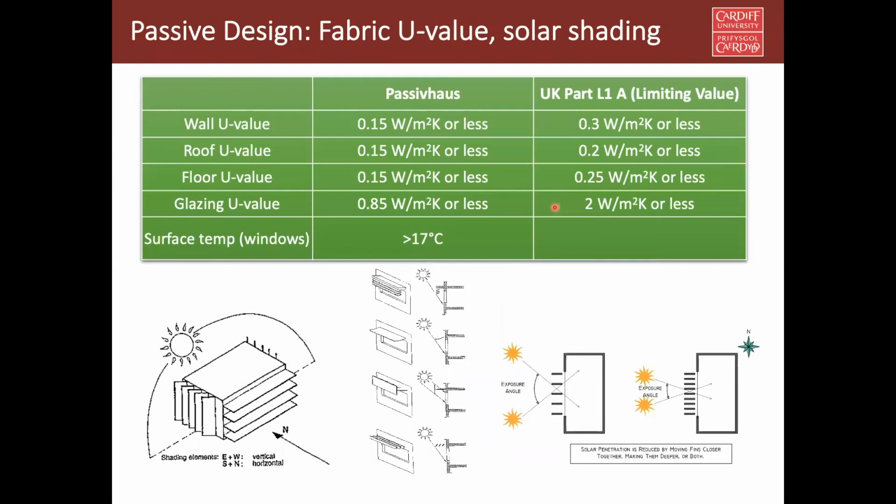The next one is thermal insulation. That's really, really important. Thermal insulation in the building envelope is the first line of defense against climate. So walls with high insulation value stop heat flux through the wall. There are very good standards these days about U values. One of them is the passive house U value, which is about 0.15 watt per meter square Kelvin, which works quite well with buildings.